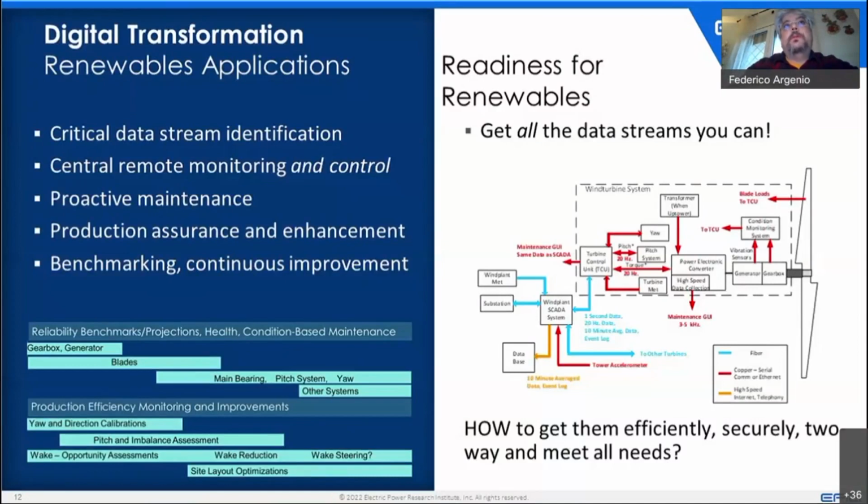Then we created a stratum with the operation named ETL, extract, transform, and load. We created an ETL between the SCADA and our central system that allows us to homogenize all of the data for the different manufacturers. The variables that we use are not a secret, they are something very classical, like electrical ones or ambient environmental measures, both from the DC and the AC side of the inverter.